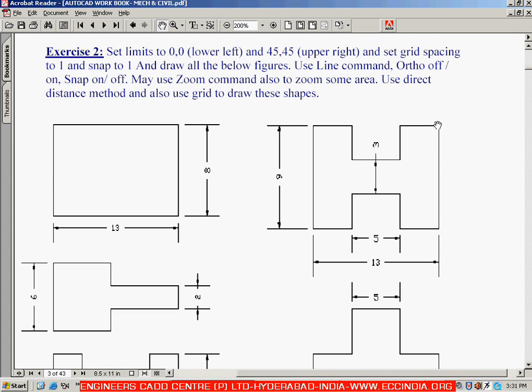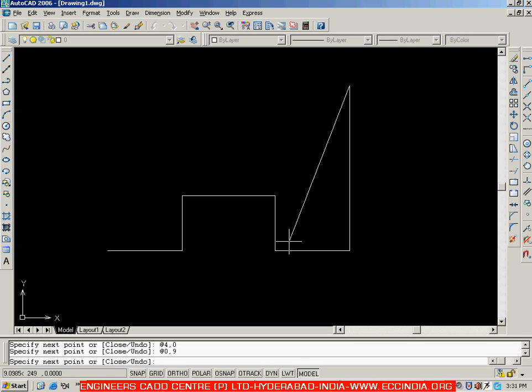And right now I am standing here, then this particular point coordinates will become -4, 0, because I have to move in the negative of x. If this is origin, from here I have to move in the negative of x, and this is -4, 0. So let me go with @ -4, 0.